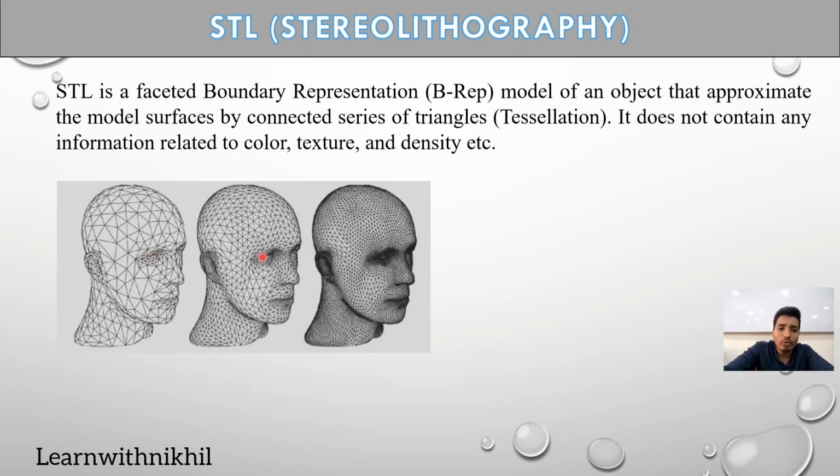Compared to this image, you can see the number of triangles has increased. It is basically like a resolution. The higher the resolution, the more the quality of the object will increase. So you can compare these three images. The triangles over here are the most, so the finer quality of the print will be there. In this one the print will not be that good. Here the print will be much better, and this will be the best quality.